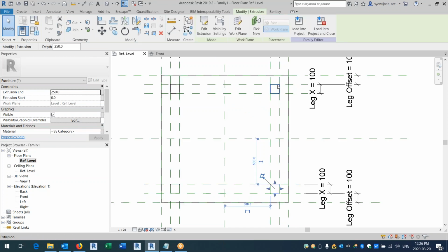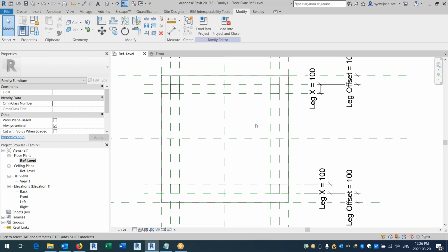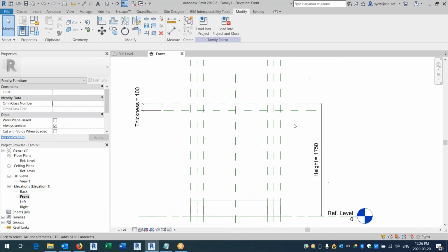You could still do it, you could assume that this leg, that leg, that leg, and that leg, you could just draw all the same pieces. But for me, I've seen so many times where a family becomes unusable because whoever created it took the shortcut, so they decided to do it as one continuous piece. Whenever this thing gets almost close to each other, it basically gives you an error, and then the family just says, nope, it quits. I cannot do it. So just keep in mind.